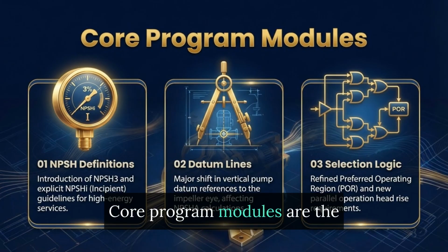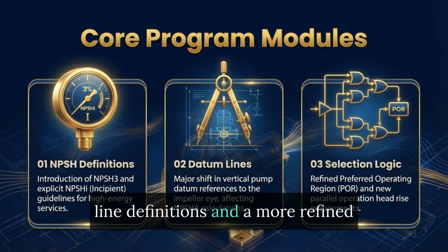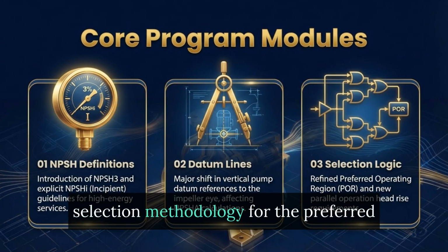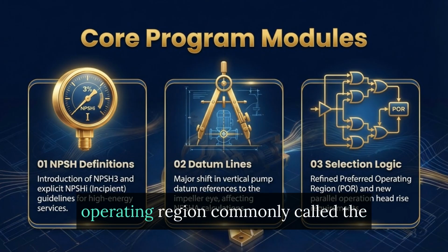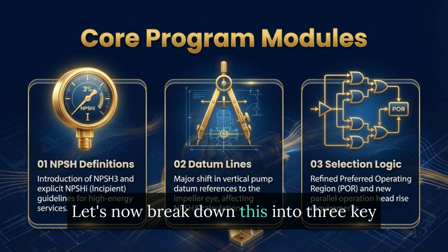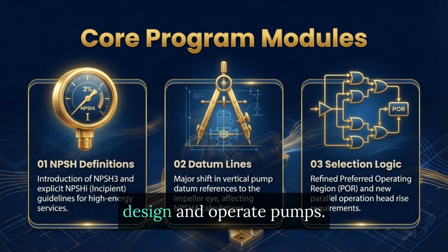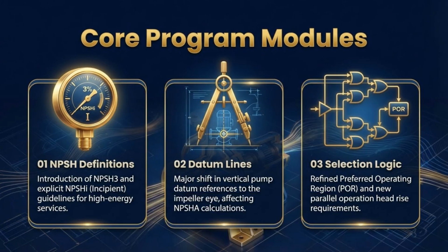Core program modules are the redefinition of NPSH, the revision of datum line definitions, and a more refined selection methodology for the preferred operating region, commonly called the POR. Let's now break this down into three key ideas that fundamentally improve how we design and operate pumps.